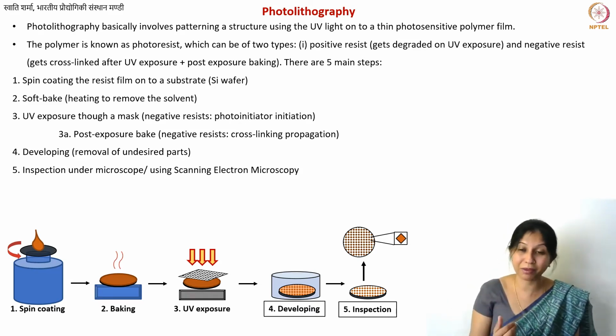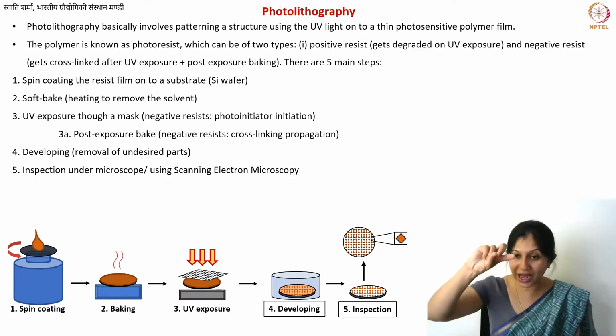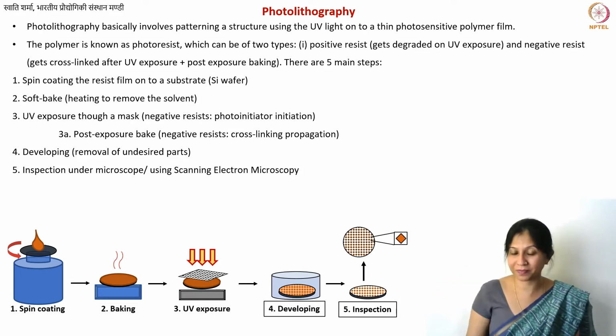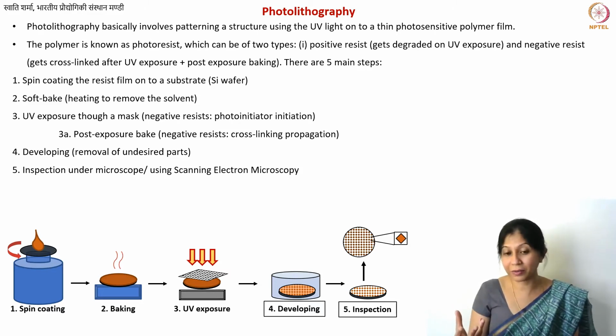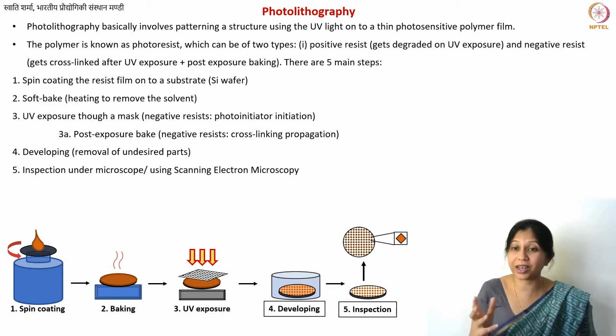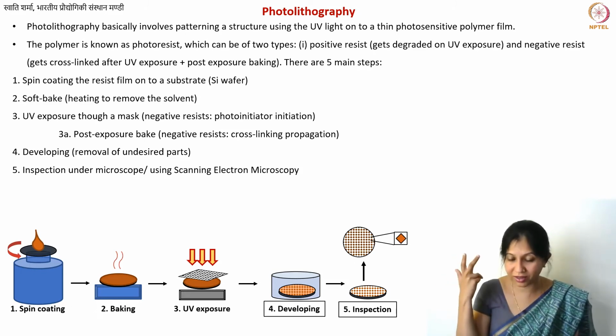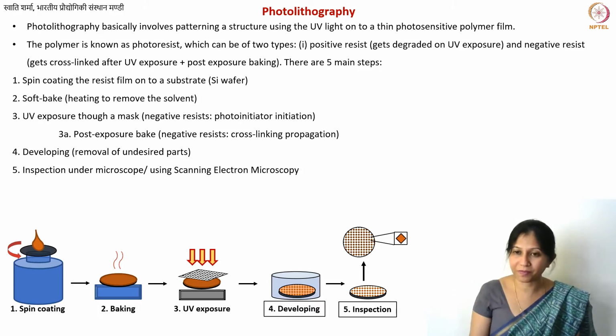But at the same time, it might be going through so much coking that you are losing the shape. So you can do multiple experiments. You can take the tip and keep it upside down also and see if it elongates. The best case scenario is that your material goes through a semi-solid phase, but not so liquid-like a phase that it loses its shape. And phenol formaldehyde resins are traditionally used for this purpose. They have been traditional glassy carbon precursors for a very long time.